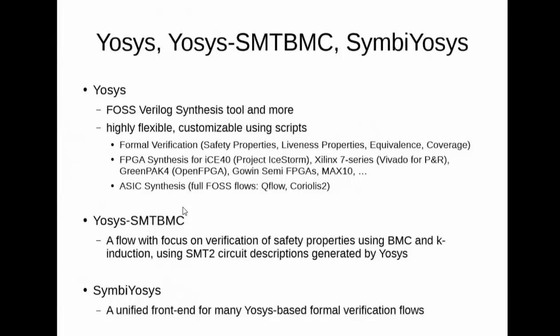So Yosys is a framework for everything you can do with Verilog, essentially. I wrote the Verilog 2005 front end, and from that I can do formal verification as well as synthesis for a couple of FPGA architectures. Most notably, probably the Lattice iCE40 FPGA architecture, because I went through the effort to reverse engineer the bitstream format for the iCE40, so we could also implement a fully open source place and route tool. So there is an end-to-end open source implementation flow for that kind of FPGAs, and also ASIC synthesis.